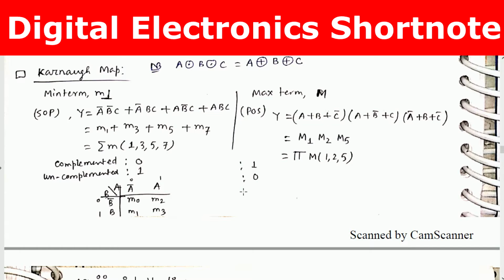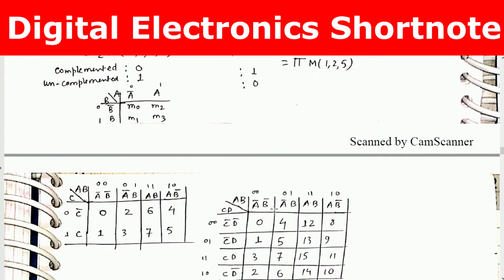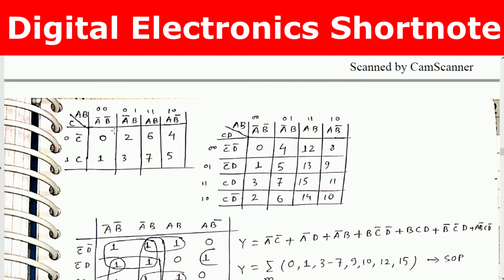So when using the Karnaugh map, we have to build a few types of tables. So this is one type of table. When you only have two variables A and B, then we write A complement, A, B complement, B, and in this way it is 0 2 1 3. Okay. Now how to remember these numbers? When you have three variables A, B, and C, we write A complement B complement, then A complement B, A B, A B complement, and this is C complement, C.